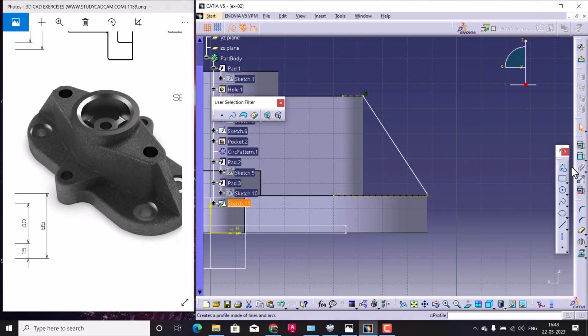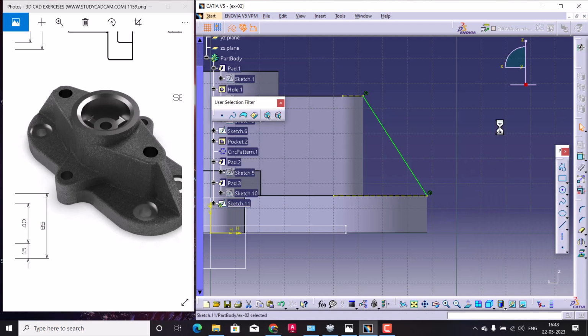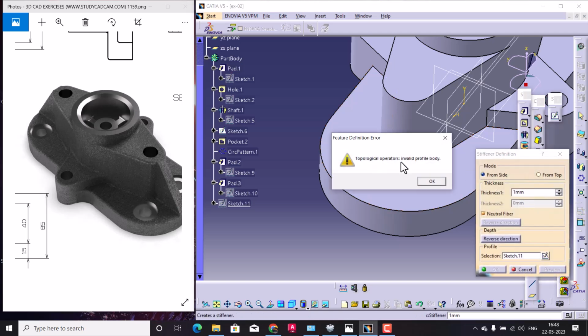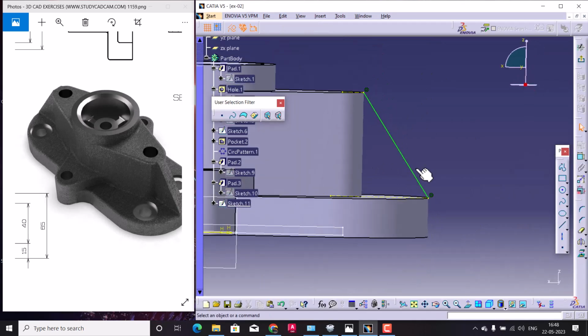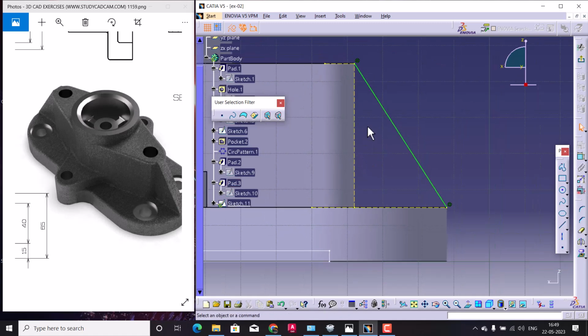So now we are making it coincident directly with that edge, but if you go for stiffener, we have the tool available here. It won't come if you have connected it exactly to the top. So instead of connecting it here, it has to come a little bit down, and in a similar way we need this reference, which you will get with respect to project 3D shell out edges. So select that. So shell out edge you have got.